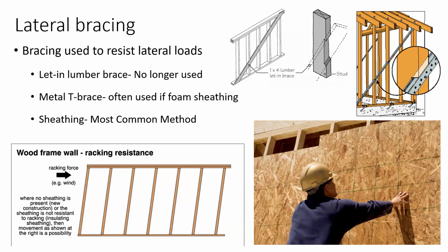So I started my career in the energy crisis and we used foam sheathing and we had to do, like, say we did 2 inches instead of 4. We would do 1.5 inches at the corner and at certain parts, and then do our 1/2 inch sheathing just to get enough OSB or plywood on there to keep that house from tipping over. You can't do 4 inches foam everywhere without the metal bracing or without putting a wood sheathing on it to stabilize it. The other downside we found by doing all our walls with foam is that if you have a vinyl sided house, people can literally break into your house with a hammer. Bam, bam, bam, bam, walk through the studs and they're into your house.